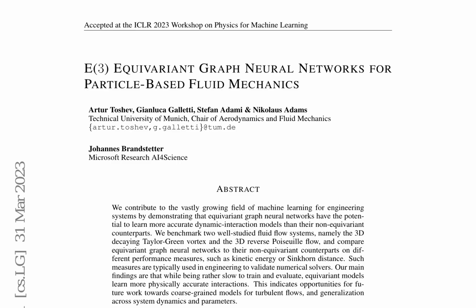Navier-Stokes equations are ubiquitous in fluid mechanics, hydrodynamics, and weather modeling. However, these equations are often analytically intractable, necessitating numerical solution schemes. These schemes can be categorized into grid, mesh-based methods, also known as Eulerian description, and particle-based methods, or Lagrangian description.